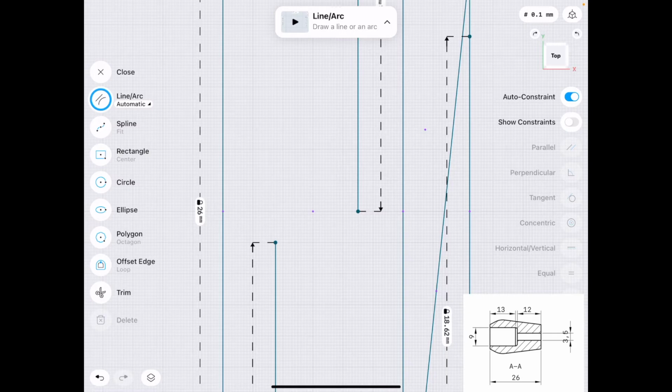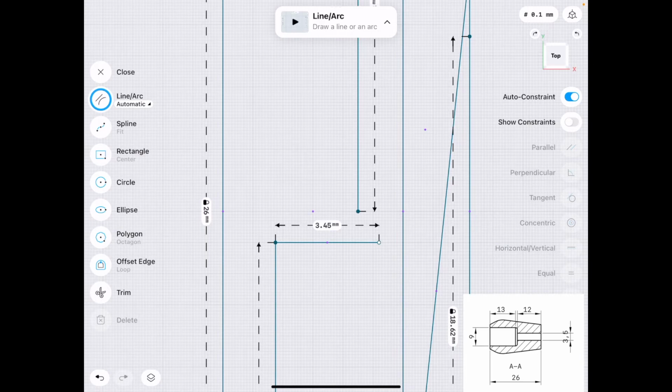And if you zoom in on the technical drawing, you'll see that there's actually a fillet there, a rounded surface. And we know that it's 1 millimeter because that's the difference. So I'm just going to do this quick and dirty here. Horizontal, going to extend that line down, vertical.